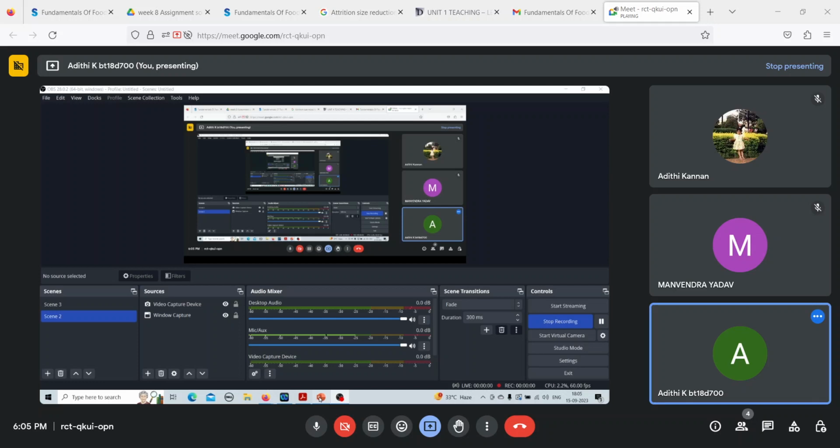So now in the second scenario, you have the Kk, you know Xf, you know Xp. From there you can calculate E in the second case scenario. That is what we'll be doing here. So Kick's law constant we calculated as 4.46, Xf is 15 millimeter. Now you want to reduce it to 0.2 millimeter, which is Xp. If you just substitute the values and calculate, you get energy as 19.3 kilowatt. This is option C.